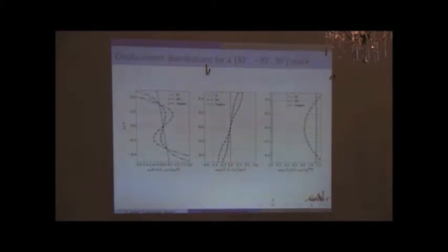And now this is for the displacements. This is U1, the in-plane displacement taken at the boundary. This is due to the in-plane displacement in the infinite direction, taken at the boundary, and this is the global deflection at midspan, U3, normalized with the exact solution because it goes very far because of the scalings. Okay, and you see the exact solution, the bending gradient approximation, and here the Kirchhoff-Love approximation.